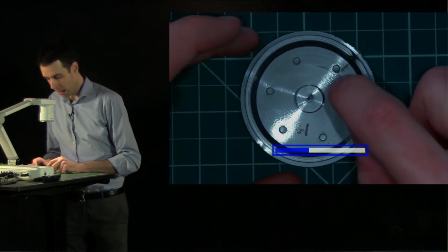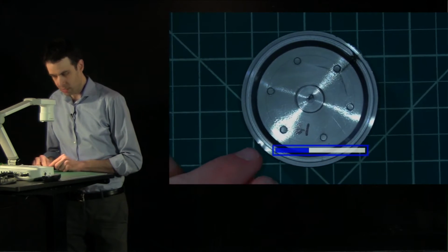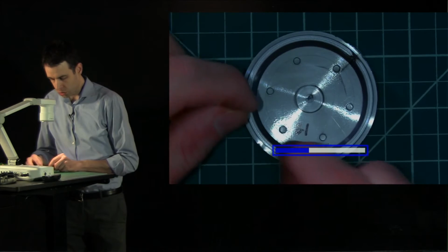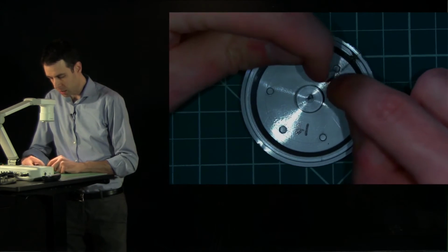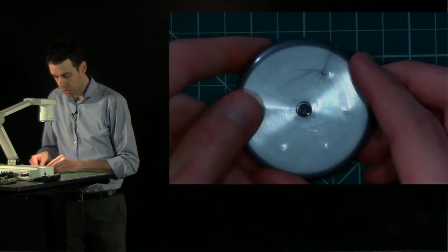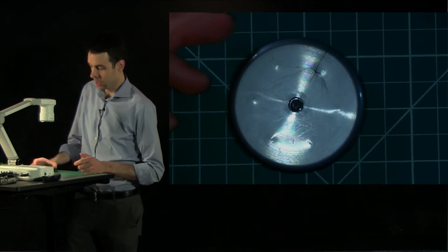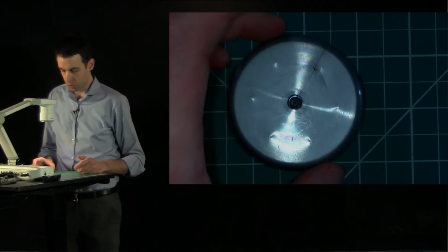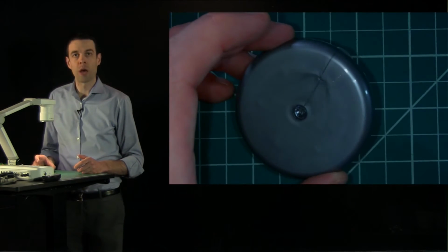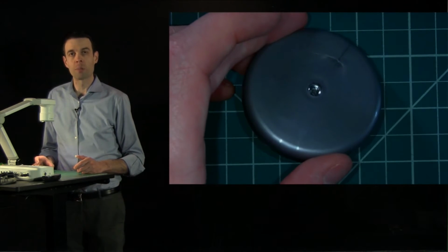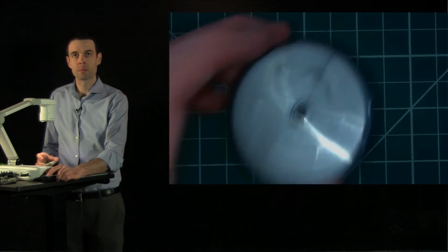And I also want to point out what's called a weld line. Because the plastic is injected over here, it flows circumferentially around, and in some cases, especially in certain colors, you see a weld line that represents where the plastic meets. And that, in some cases, is a defect that you want to tune the process parameters to help eliminate if your visual appearance is important as well.